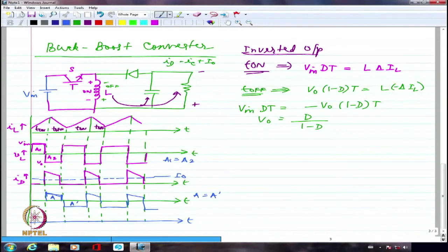then that will give me the output current's average because of that. Because the diode is the one which is even providing for the capacitance. Right? Think about it, because capacitance, where will it get the energy from? It is getting from the inductance. But the inductance is essentially passing it through the diode. But I cannot say the inductance average current is same as I naught.